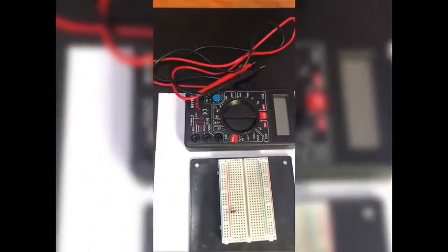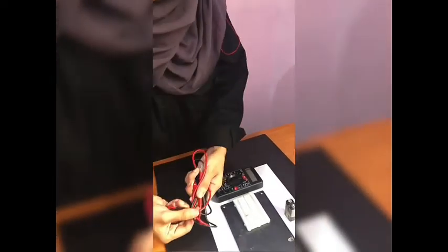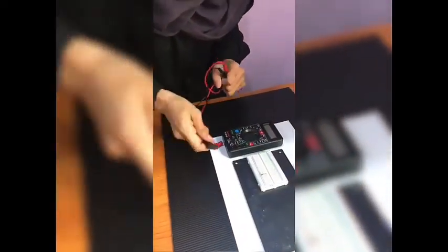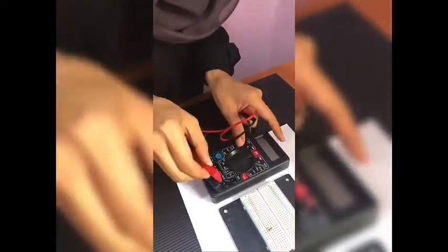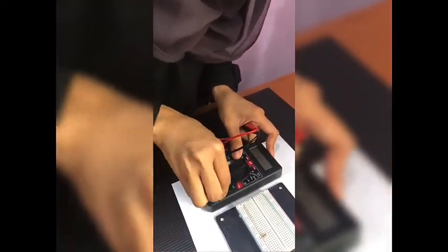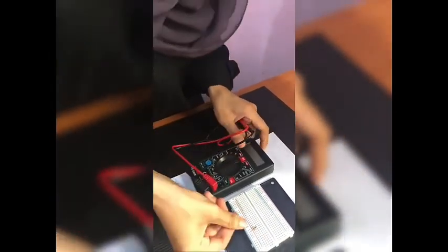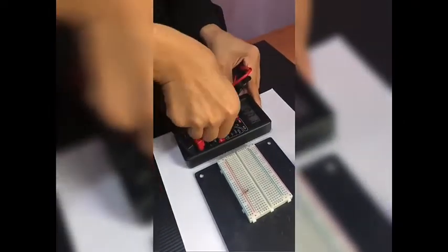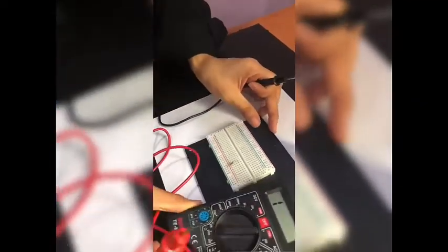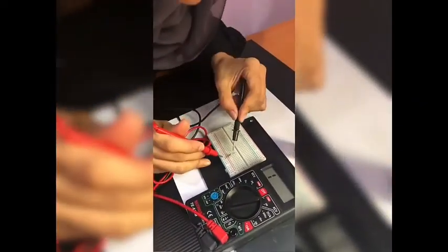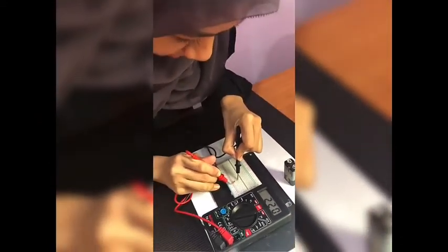and multimeter. Two probes are plugged into two ports on the unit. First, we plug in the black probe that must be connected to the COM connection on the multimeter, and the red probe connects to the connection on the multimeter that is marked VmA. To measure the resistance of a resistor, turn the multimeter dial to the ohm marking. Connect the two wires to the two ends of the resistor. The value will be shown on the multimeter display.